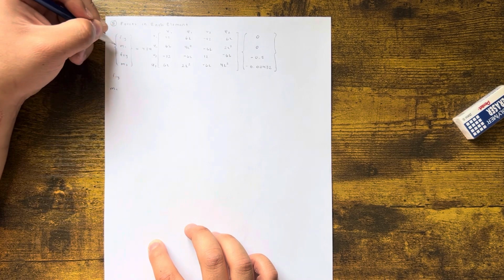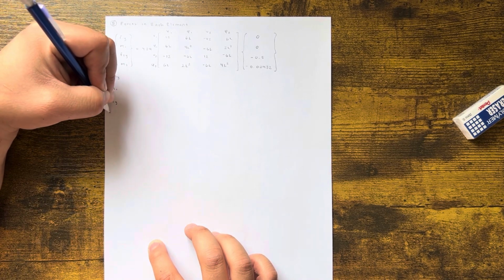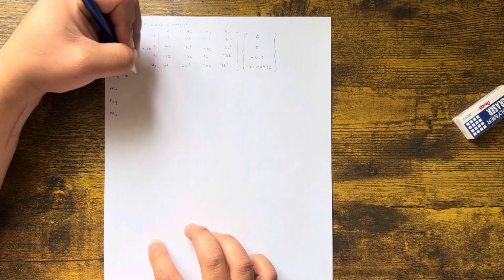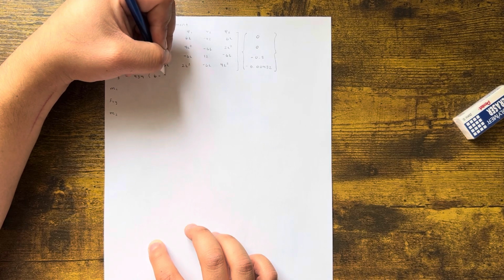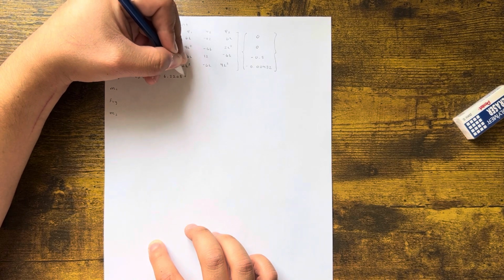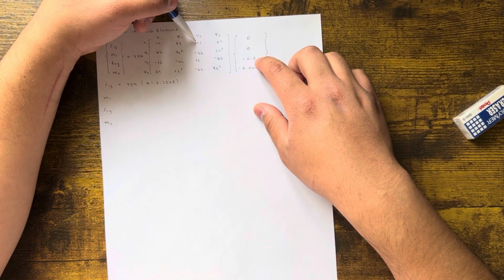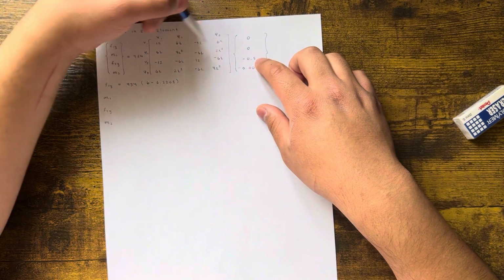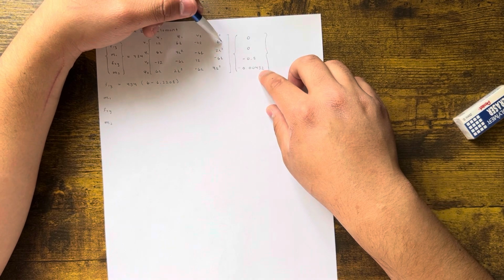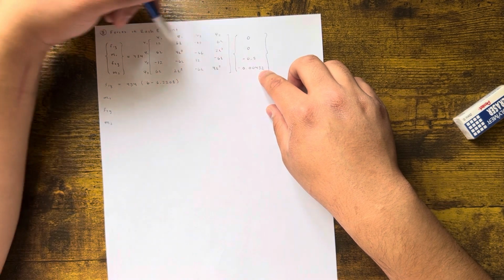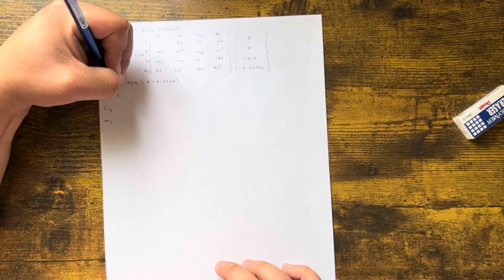You're going to have 4 equations, 4 unknowns, right? But this one's not that bad because you already know everything. You're just plugging and chugging. So 434, and then you're going to have 6 minus 6.2208, okay, that's for F1y. It's 12 times 0, 6L times 0, minus 12 times negative 0.5, which is 6, and then 6L times Phi2, okay? In this case, we know L is just 240. So we know all this, and we know all of this, so that means we should know all of this. So that's the setup right there.